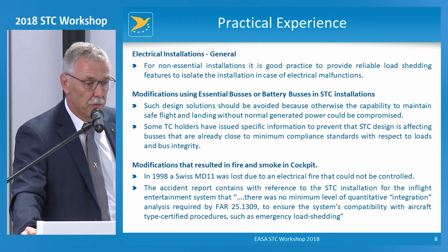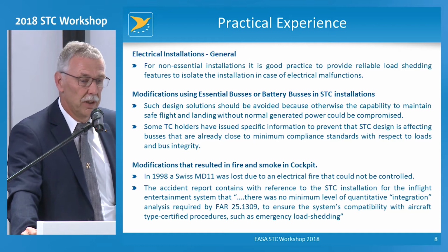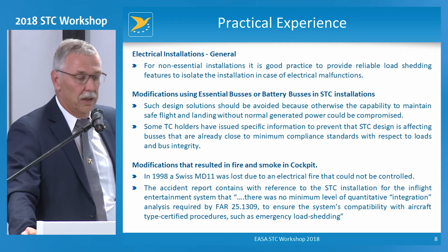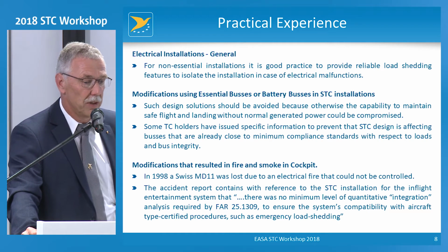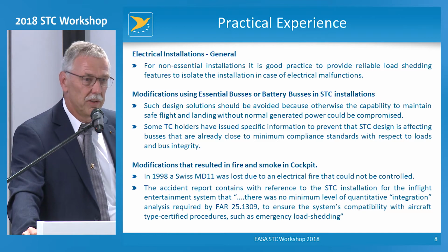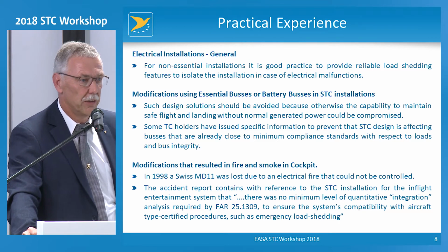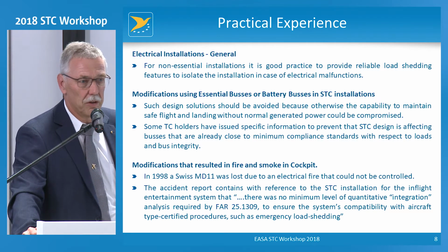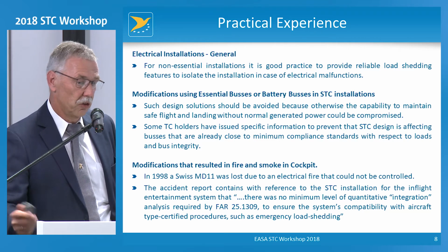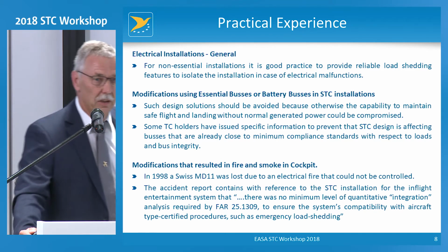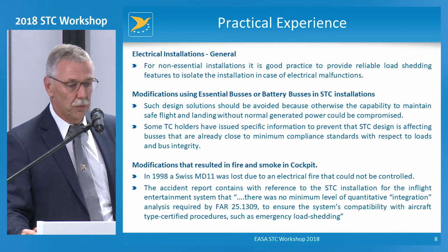What can happen if something is not properly load shed or put on an essential bus? This is on the lower part of the screen. It was an accident of an MD-11, which was related to an STC installation of an in-flight entertainment system. It burned under the cockpit, was non-contained, and the aircraft crashed. And this was because the overall integrity of the STC was not properly designed.